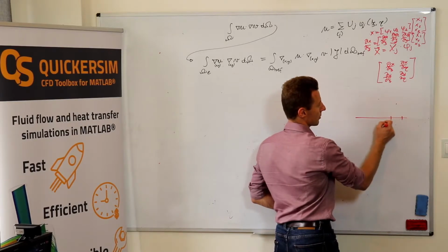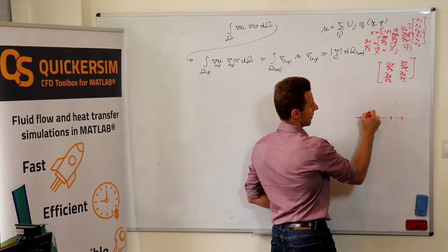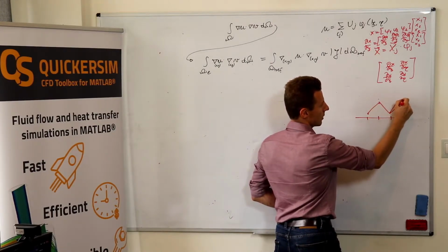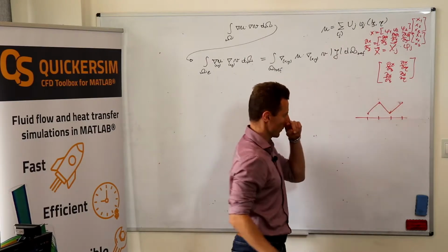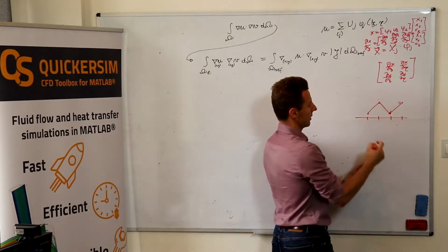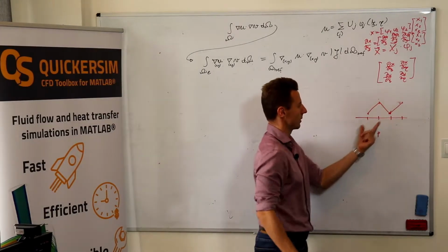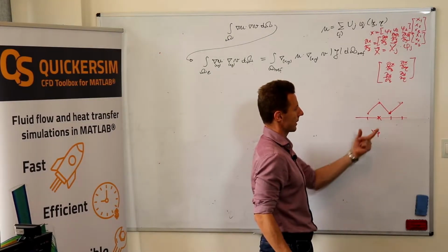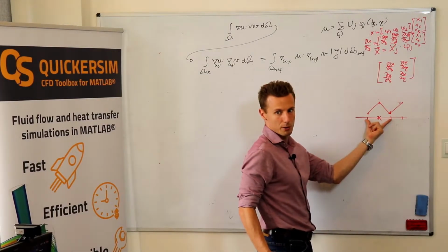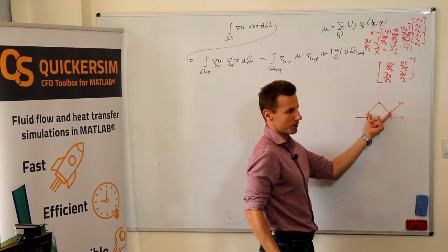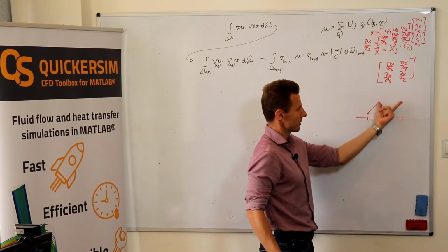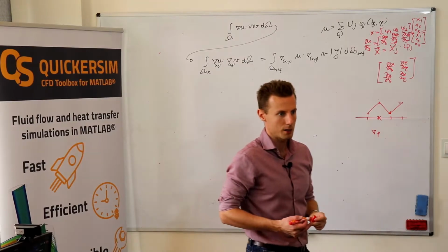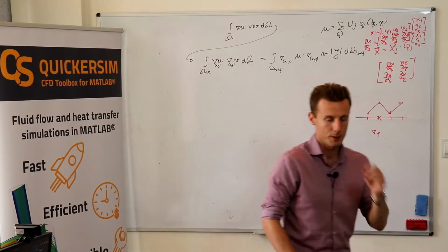if you do the discretization wrong, we have seen that having such a pressure distribution with absolutely arbitrary values, if you discretize the pressure gradient term, discretizing the Navier-Stokes equation at this node, you use for pressure gradient calculation these two values, then we remember that, well, the pressure gradient is 0. Well, this one is also 0, but you've got completely arbitrary values in every second node. So there is some singularity in the system.